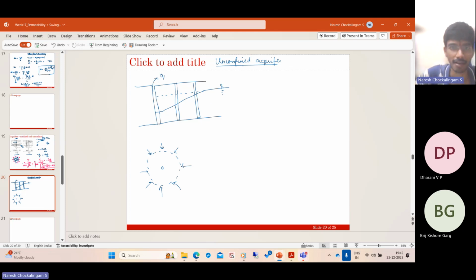Now here, when you do a borehole, the water is not going to rise because this has a free surface. The entire stratum is pervious. So at this free surface, the pressure in the water is equal to the atmospheric pressure. Therefore, when we make a well, the water surface is exactly where the free surface is. It doesn't rise above the free surface. So let this height be h1 and let this height be h2.